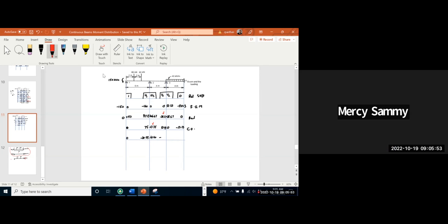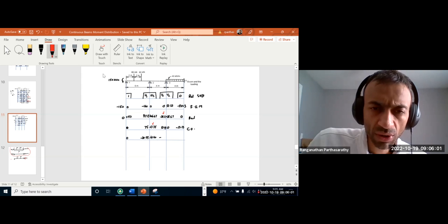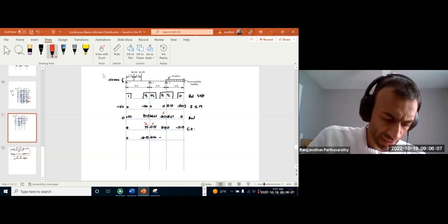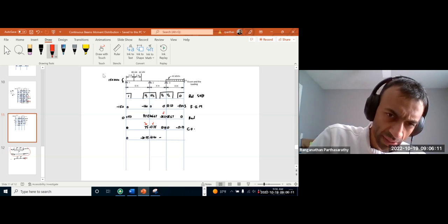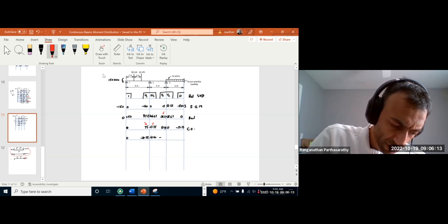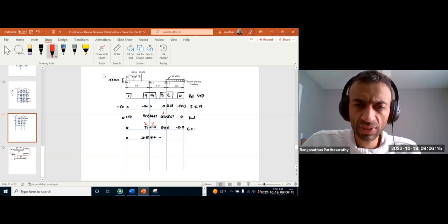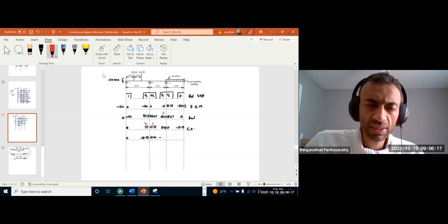Yeah, but did you see that something will be unbalanced when you're adding them? Yes. So the unbalanced is because this side is positive 75, this side is negative 13.35. So we have an unbalance of 75 minus 13.35, that is positive 61.65. So I'm putting in negative 61.65 in this step.